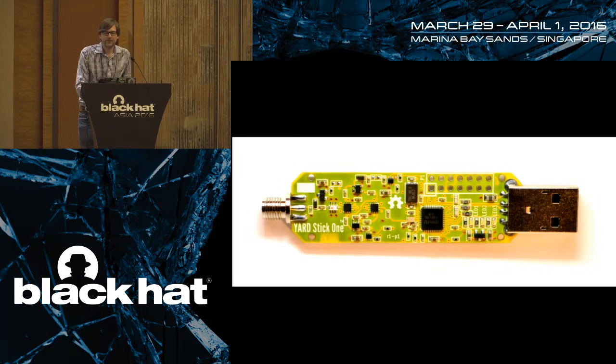And the key thing to know about the CC1111 or any of these wireless transceiver ICs that are on the market is that they provide a digital modem on a chip. So all the modulation and demodulation is done in hardware, not in software. With SDR, we do that stuff in software. With something like this, we do that in hardware. And so it's more limited.